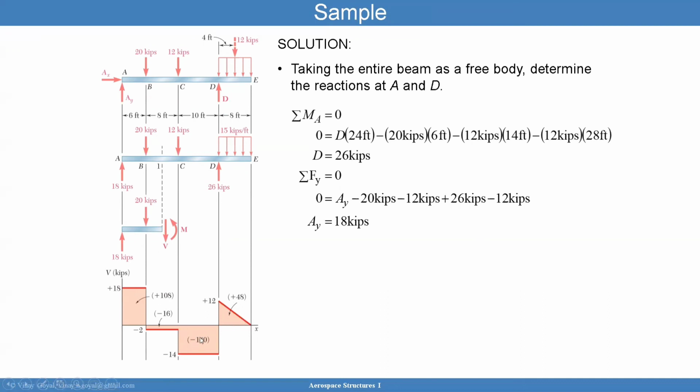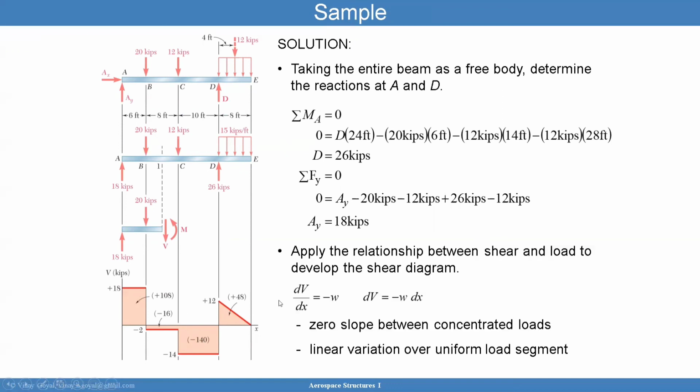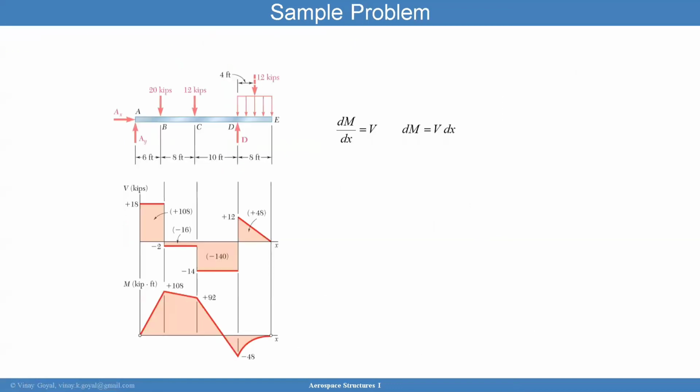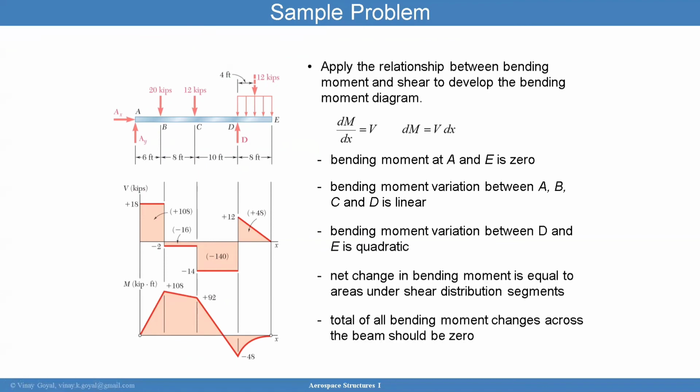So once I have the shear diagram, you can also integrate that. And if you integrate this constant value, you get this moment, which is linear now. And so again, you have to do each of these, integrate the moment. So dM/dx equals V. So integrate this equation. I apologize, just want to show how it's done. So by integrating the shear, you can construct the moment diagram fairly easily.